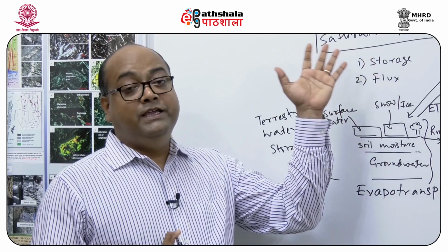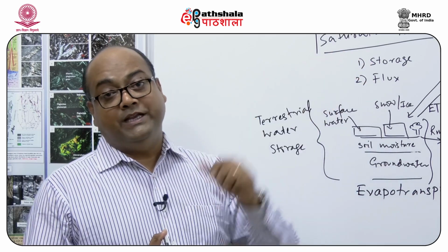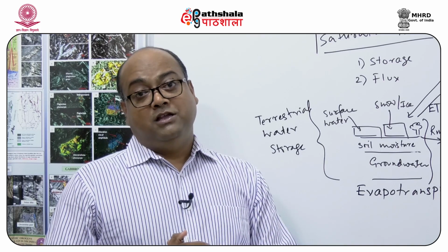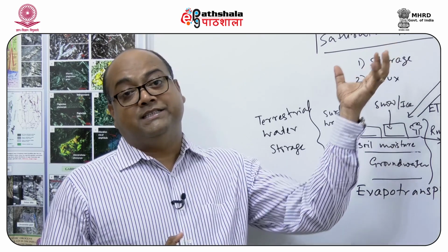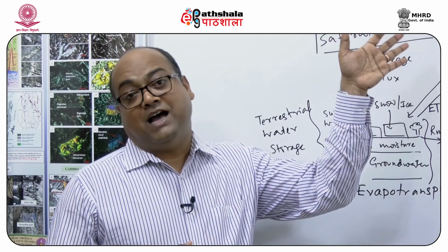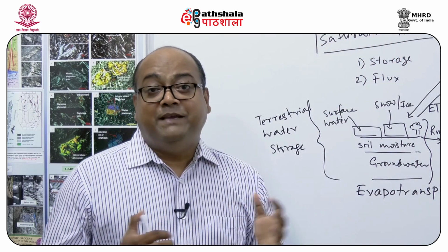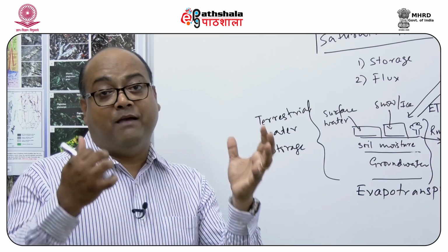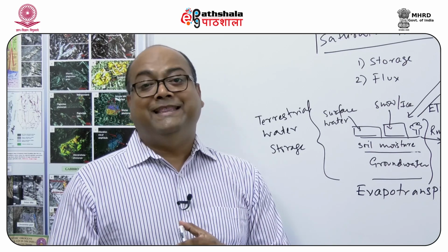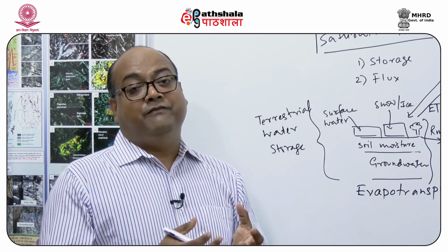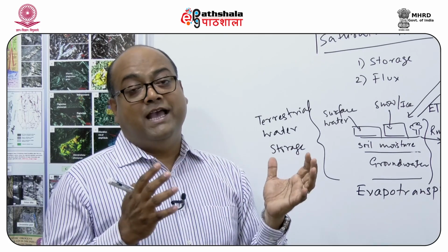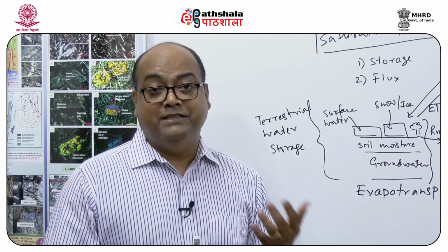Now, how it reaches 100% relative humidity is that if we reduce the temperature of the air parcel, the saturation humidity starts decreasing. And once the saturation humidity starts decreasing, the relative humidity starts increasing. So the basic process required for precipitation to take place is that we need to cool the air parcel. And that is done by raising the parcel of air towards a higher altitude in the atmospheric column, because the temperature, as we know, in the lower parts of the atmosphere decreases with height.